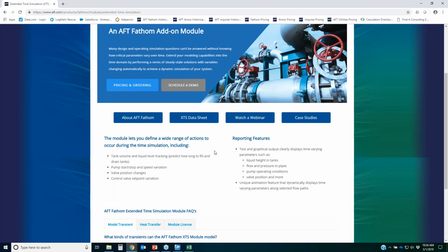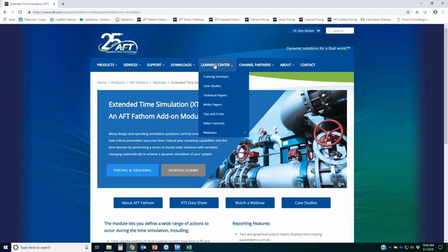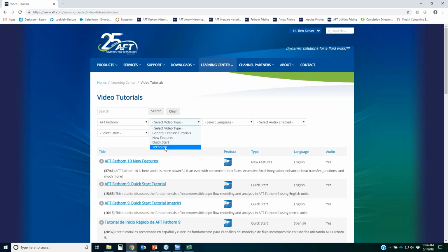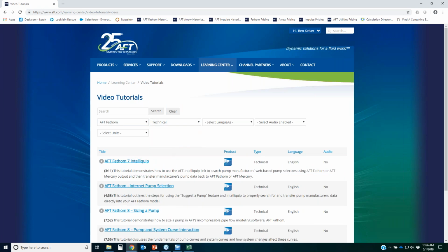I'm not going to go through that process right now, but if you were to go to our Learning Center and then video tutorials, you can do a search for Fathom and then narrow this down by technical videos. And this is the video right here that I'm talking about. It's called AFT Fathom Internet Pump Selection. So if you watch that video, it'll show you how you can easily use Fathom to select a pump from a real vendor. That way you can get a real pump curve loaded right into Fathom.